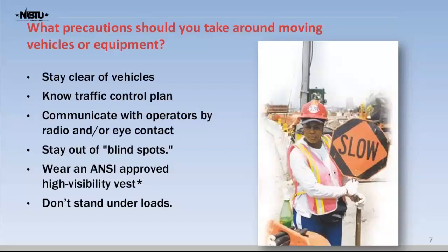Even if you're not working with it, with a truck as it's coming onto the site, don't walk into the roadway without making eye contact with that driver. And, usually, waving your hand, making some sort of an effort to make sure they see you, and you know they see you by making eye contact, is a critical thing.